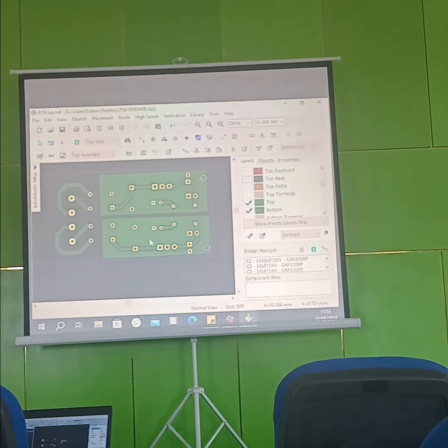Normally, when you fabricate this board, this part is conductive, but it has been laminated with green film, insulating the trace. That green film insulates the trace, but it won't insulate this soldering point. You understand me now? If it is not insulated, if you try to solder this point, the lead will spread over the trace. Are you getting me?